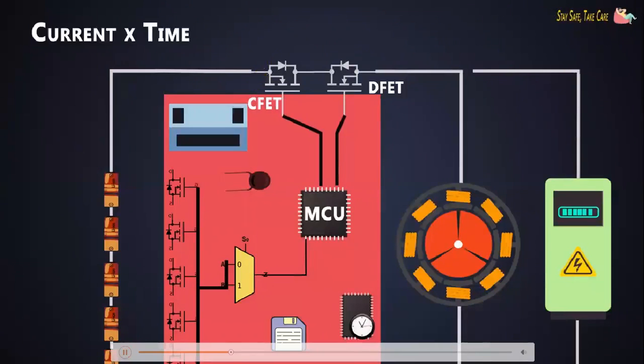This block keeps track of the charge coming in and going out of the battery pack. For measuring the current, a current sense amplifier and an MCU which has an analog to digital converter are used. A very low value current sense resistor is connected in series. The voltage drop across this resistor is measured by the amplifier, which then amplifies the signal. The microcontroller measures the voltage and calculates the charge according to the time. The discharging and charging current is sensed by the direction of the current.